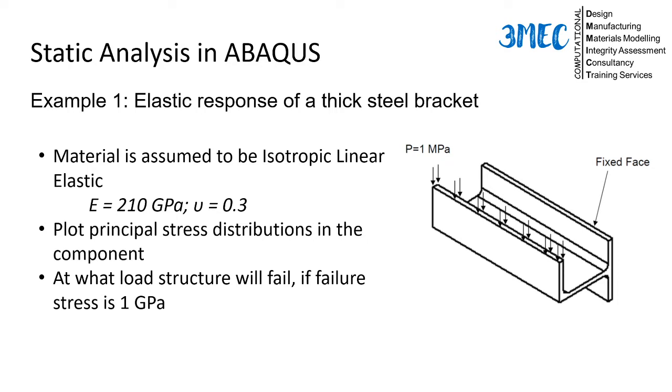In the context of integrity, when we talk about failure stress, it's not the strength at which the material really fails, like ultimate strength, but the yield strength at which you will have permanent deformation in the structure, and your structure's integrity will be compromised due to the permanent deformation. In reality, if you look at different design codes, you will have this failure stress as the yield stress times some factor of safety, and that will give you that value.